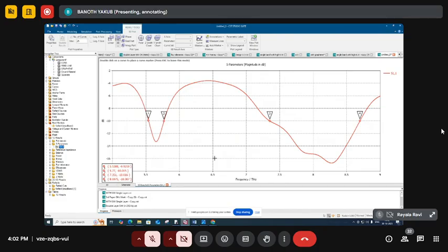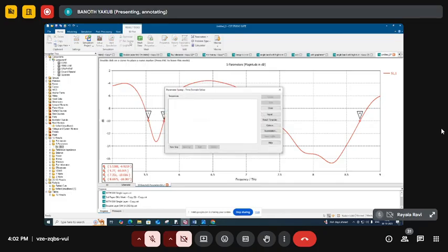So that last question we are asking is about the parametric analysis, sir. I will show that and I will complete the session, sir. So go to the home. Here the optimizer and parametric sweep options are there. Just click on the parametric sweep. Here click on the new sequence and click on the new parameter. Here you can see, sir, the names of the materials we added in the particular antenna design. All options will be shown here.